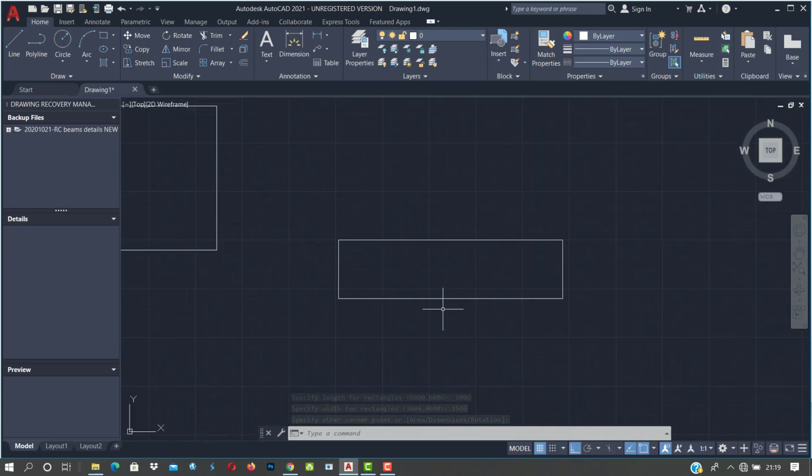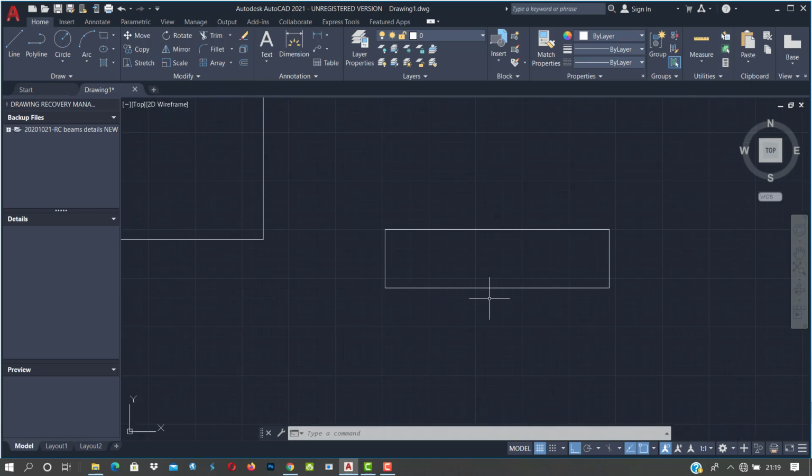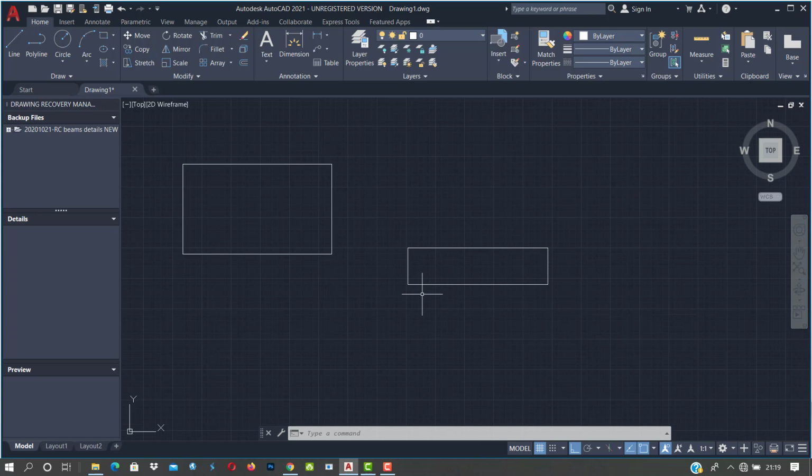And there are other ways. As time goes on, we are going to learn it. For now, you've created all the 4 basic objects: line, circle, arc, and rectangle. So you should be happy about yourself. If you want to erase all what you've done on the screen, you can just type the erase command on your command line.